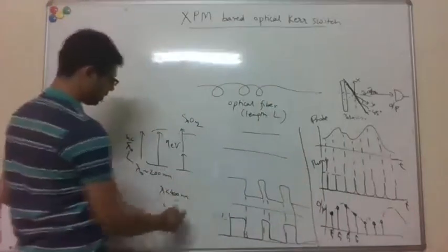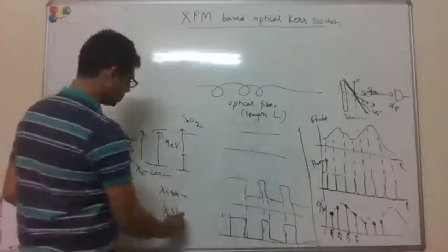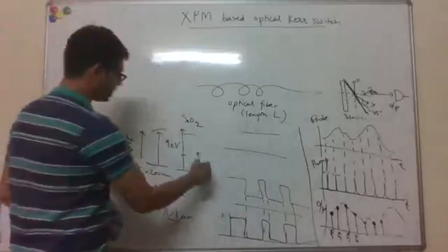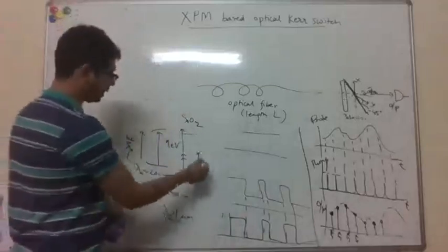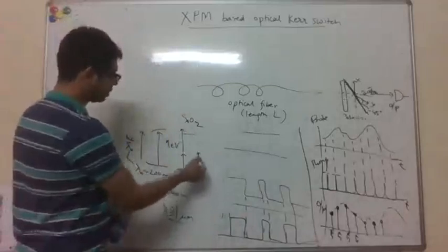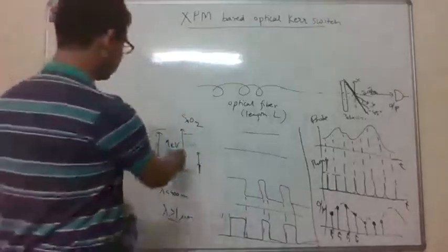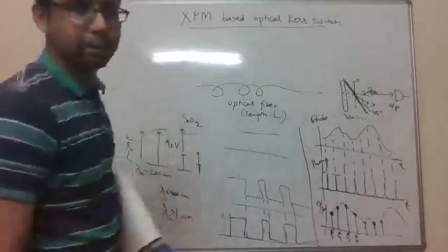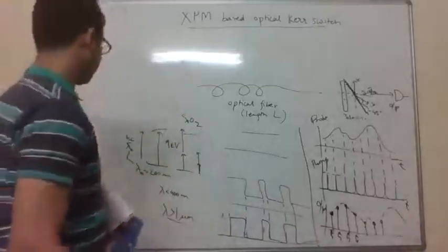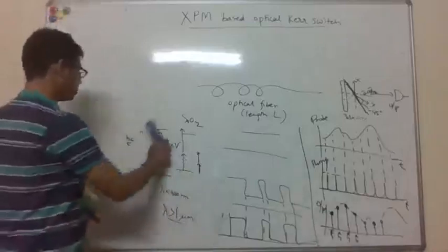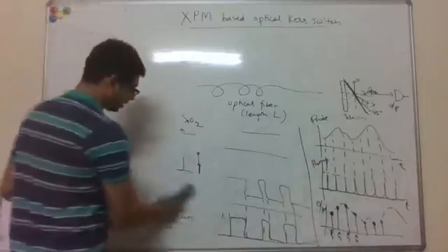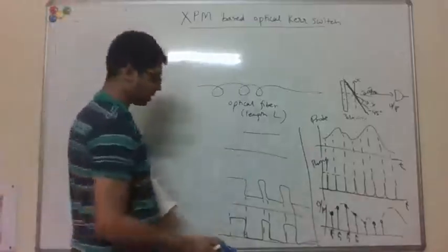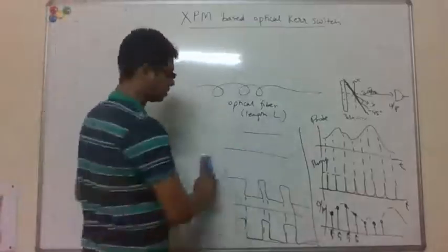But typically these are done at infrared wavelengths, a micron or longer. So the imaginary part of chi3 is 0, because just from energy considerations you cannot get 2 photon absorption. We discussed that you can get 2 photon absorption only at frequencies larger than half the band gap. But if your wavelengths were such that there could be 2 photon absorption, then you take that into account, and that would of course distort your performance.